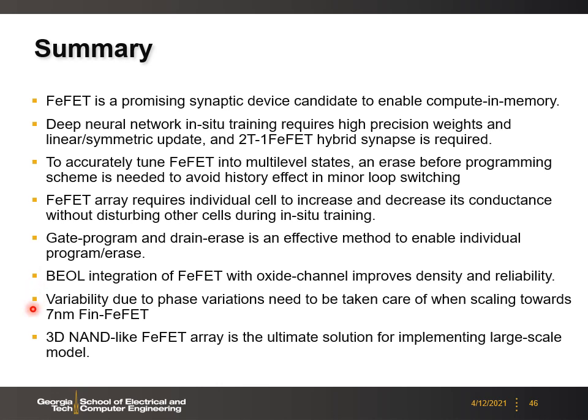The variability due to the phase variation is still a concern, especially when we scale the FeFET to more advanced technology nodes. And the 3D NAND-like FeFET array is believed to be an ultimate solution for implementing large-scale neural network models up to terabytes.